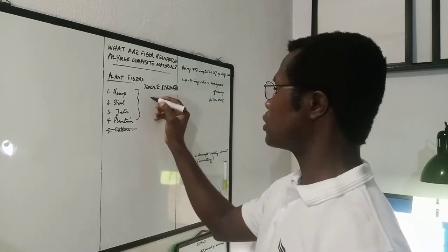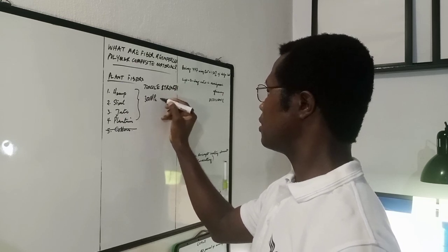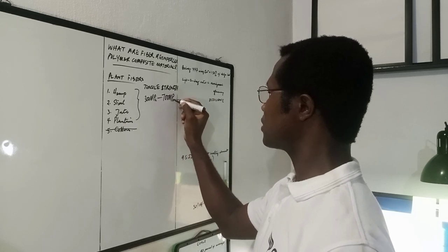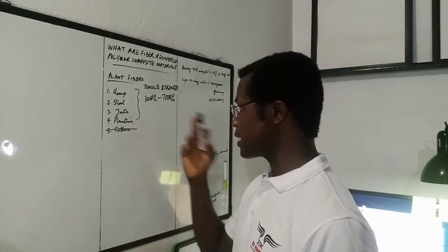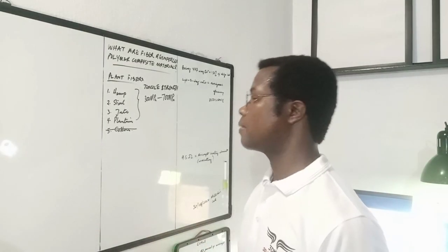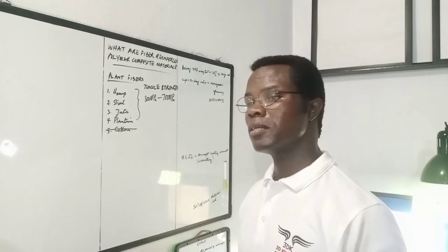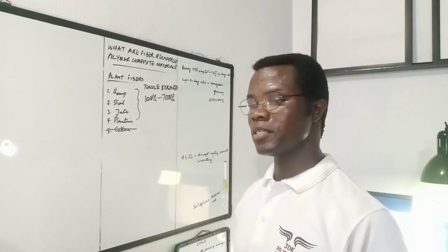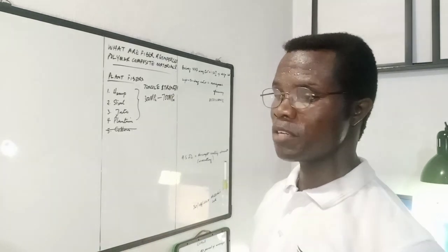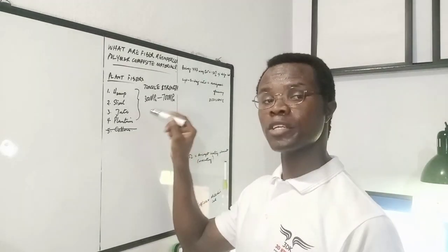In general, for tensile strength, these plant fibers fall between 300 MPa to 700 MPa in the numbers, in the tensile strength numbers from mechanical tests carried out on these fibers. There's a lot of variation. It depends on what species, the extraction method, whether the fibers were treated or not. There are a lot of reasons why that create lots of variation here.